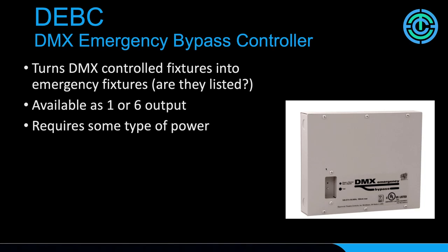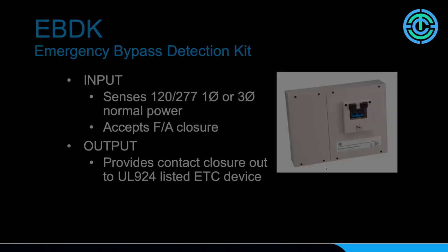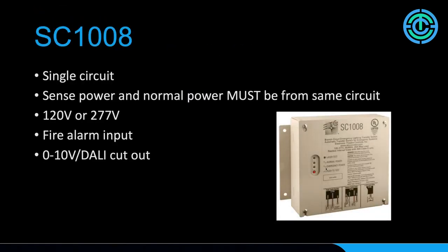So this device, as well as a couple of our others, also has the ability for remote testing. If you go back just a couple slides, our SC1008 has, because most of these would be installed in the ceiling, a laser test input, so you can take a laser pointer with you. Because you can't climb up a ladder, you can shine a laser at it and it'll run a test and transfer the circuit for you.